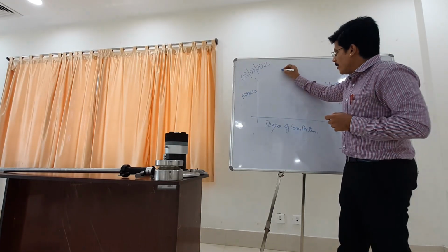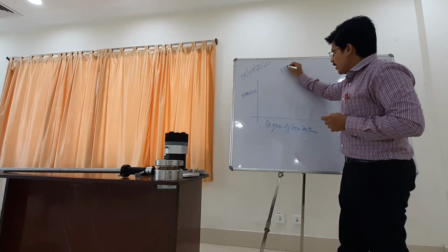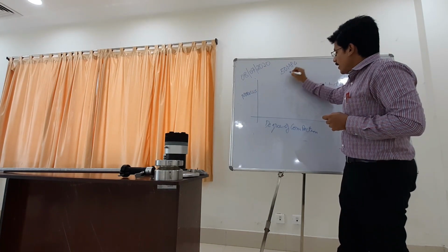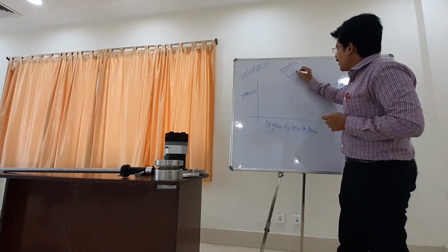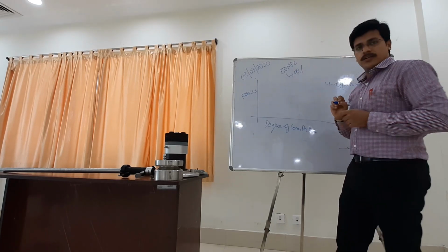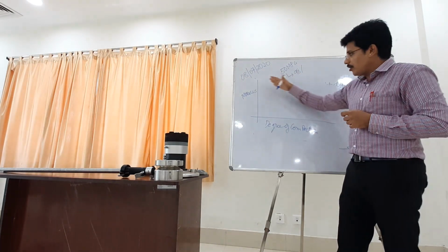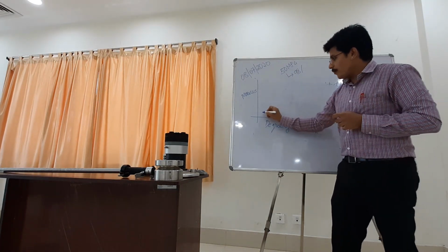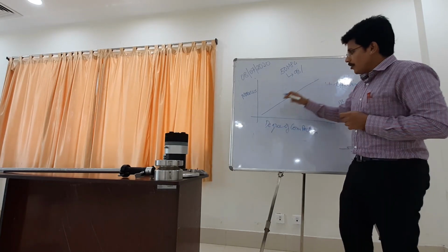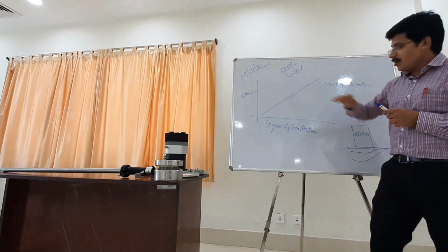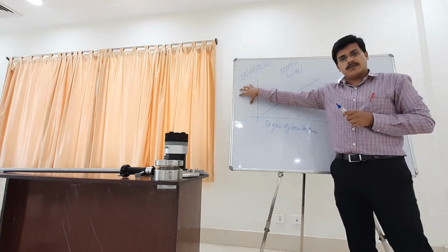Let's say you design a 50 MPa modulus, design modulus, achievable at, let's say, 98% degree of compaction. So when you do testing in the field, we can compare depending on this particular curve. If you increase the degree of compaction, you get higher modulus. Depending on this kind of curve, we can determine what is the modulus achieved in the field through degree of compaction.